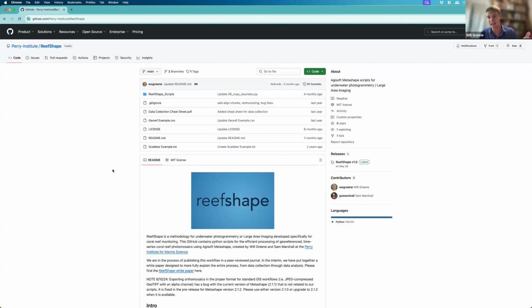And in our experience, the end data quality is really high using this process because you have a lot of overlap and you also have a lot of information about the oblique surfaces. But on principle, you're totally right that you could do a set of nadir top-down passes and then oblique passes after that. It's just about time underwater, and then processing efficiency. How many photos you have in sum total dictates how long the process will take on the computer. So being as efficient as possible while making sure you have no gaps in your data allows the process to be executed quicker on the computer.